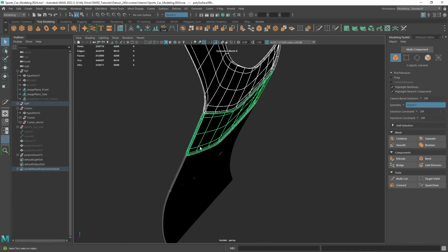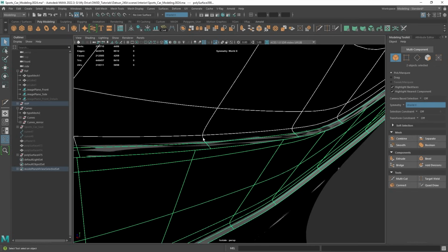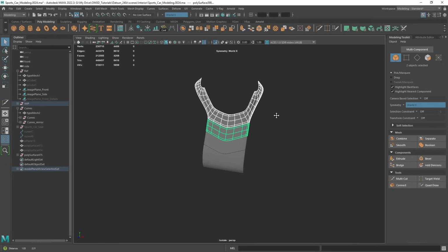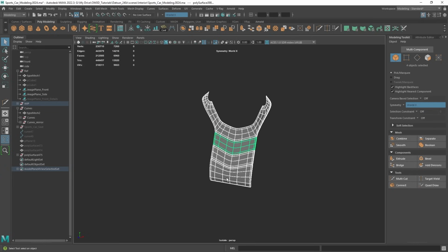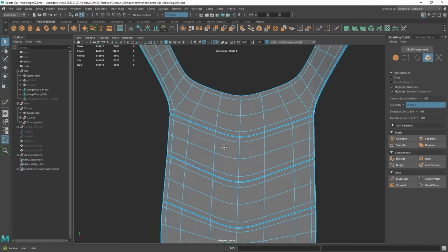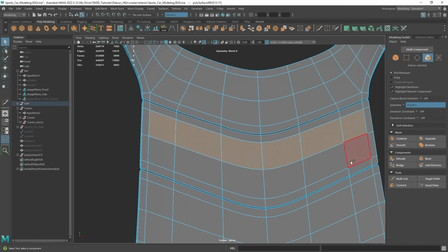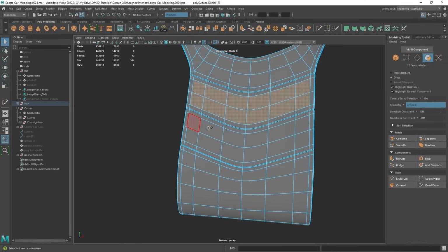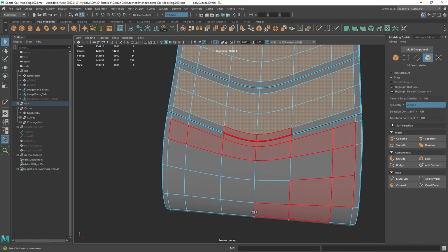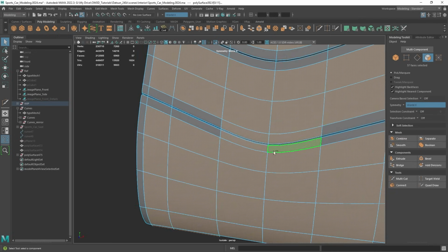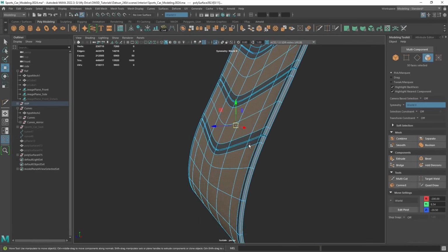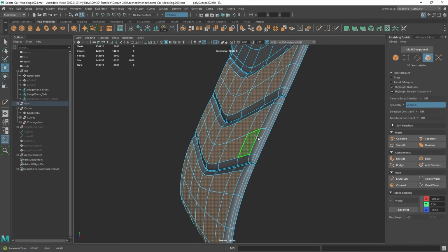Because you want to be careful not to merge things, because these are overlapping. So if you combine and use merge vertices, then you get overlapping faces, which you don't want. So instead, I keep things separate. I select the panels, and then I grab the faces. And now this is where our beveling helps, right? So you can see that I can now grab the inner pieces. So if I hold tab, you can actually just paint spray that and control click what you don't want, and you get something like this, right? And of course I'll deselect what I don't want. And if I do it for these center inserts now, hold control and just middle mouse move it, look at that.